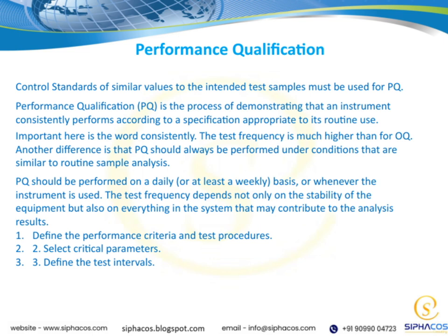PQ is all about demonstrating that our instrument consistently performs according to the specifications that match its routine use. And by consistently, I mean it should perform reliably every time under typical working conditions. One key point to highlight is that the test frequency for PQ is much higher than for OQ, or operational qualification. This makes sense because routine performance needs to be monitored more closely.